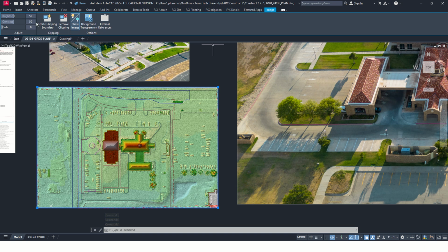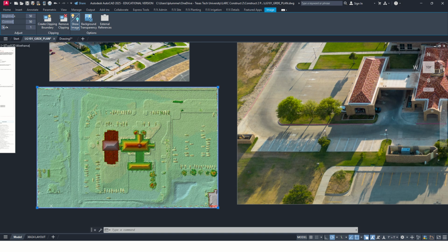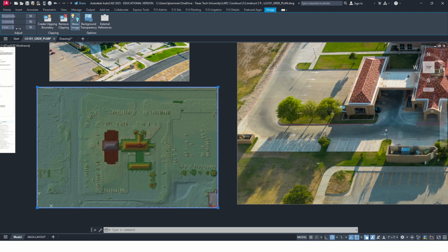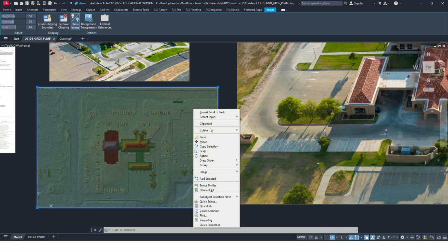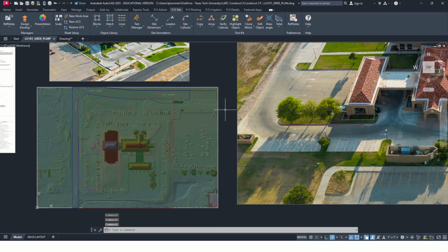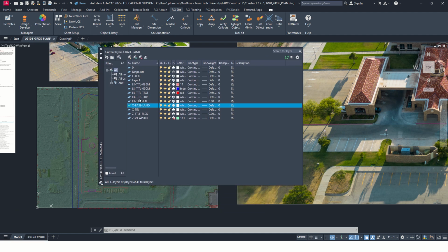This ribbon will automatically unroll and fade it down to about there. I guess like 50 or so, 60% is good. I'm going to just right click again, if this draw order gets finicky, and send to back. Now what you want to do is come over to your layers and you want to lock.